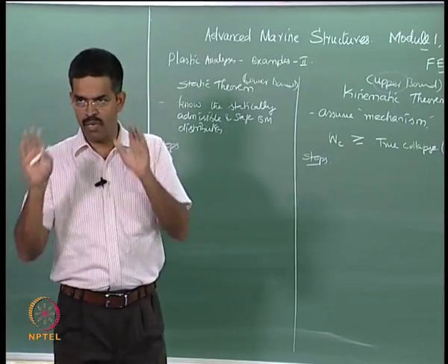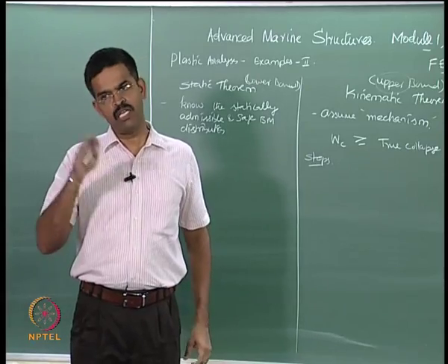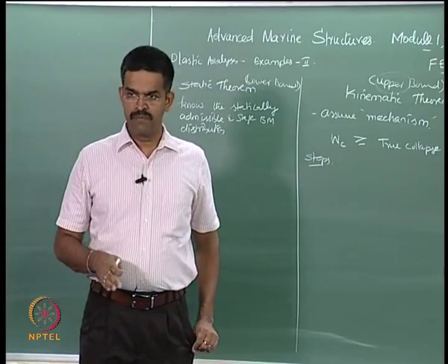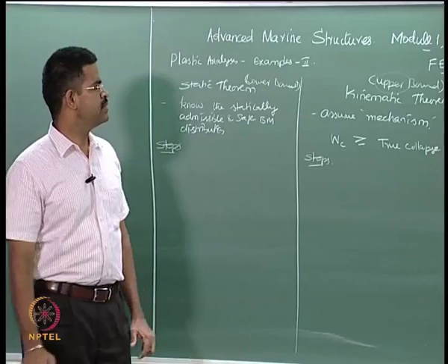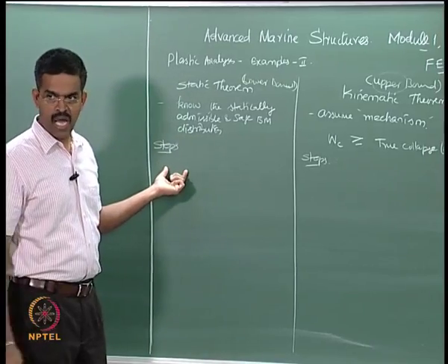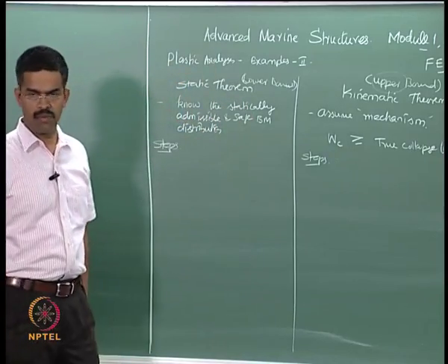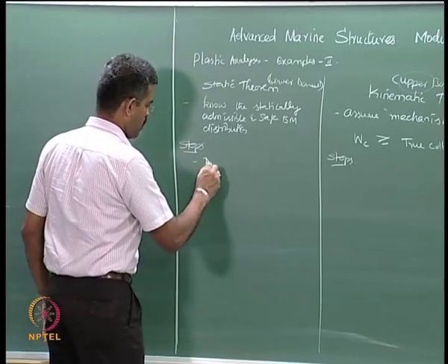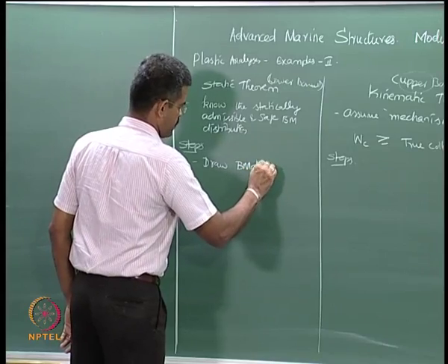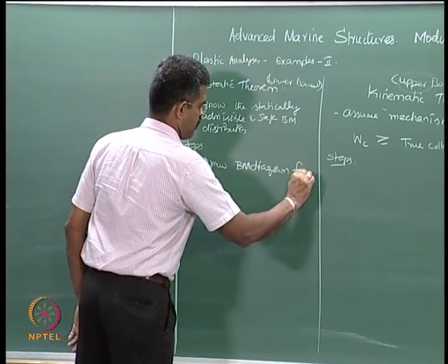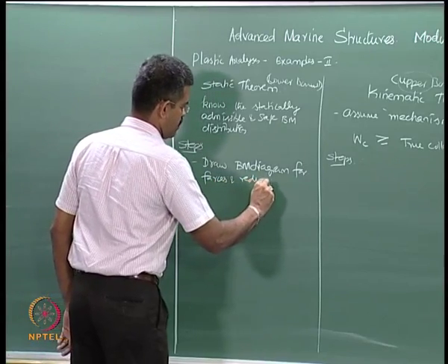All these loads have variabilities and uncertainties, these are all called working loads. I multiply this with a factor, make them factored loads, then apply them to the structure. So the steps involved in this case are, both the theorems require a structural system and a set of forces or loads coming onto the system, in this case draw the bending moment diagram for external forces and redundant forces.